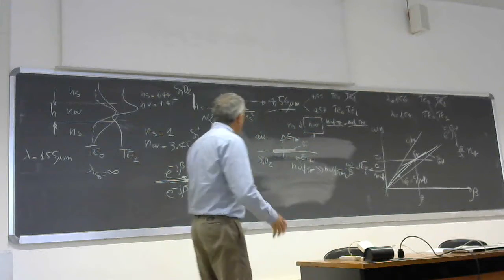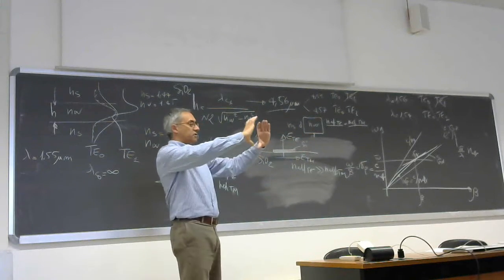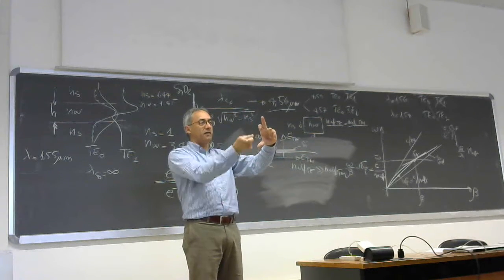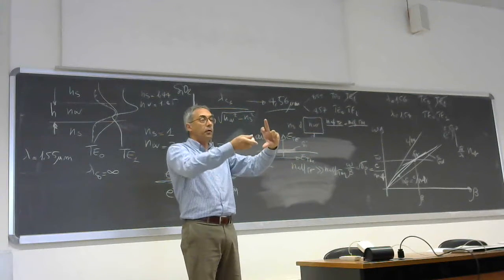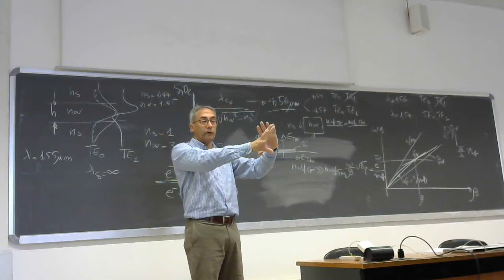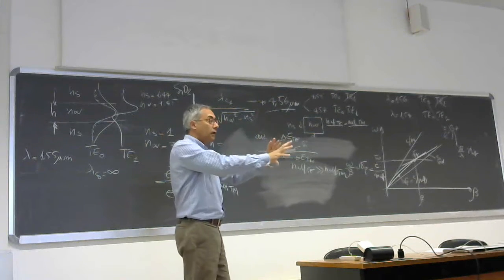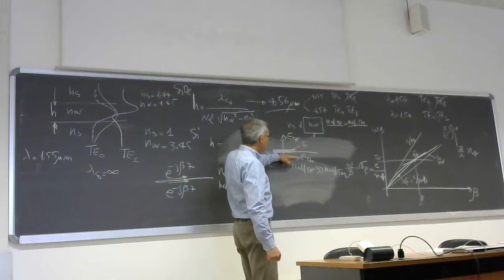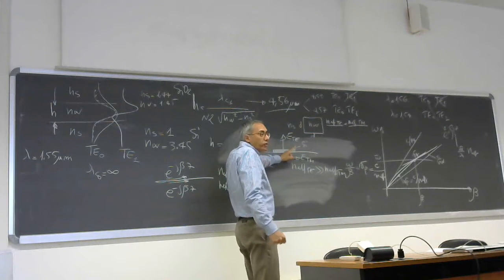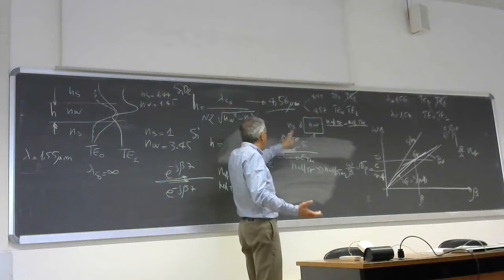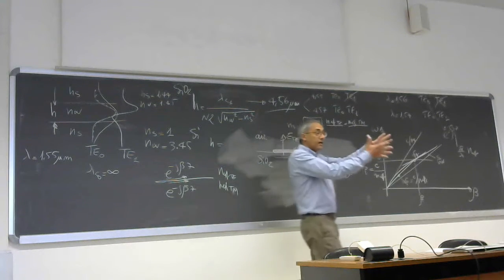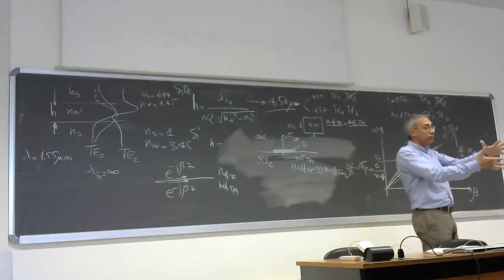So, if you arrive with an optical fiber that is a cylinder and you don't control the polarization, you don't know the polarization of the light that arrives on your waveguide. So you can excite the TE, you can excite the TM, or you can excite both. In general, you excite both because you arrive with a strange polarization. So you excite both solutions, both modes.